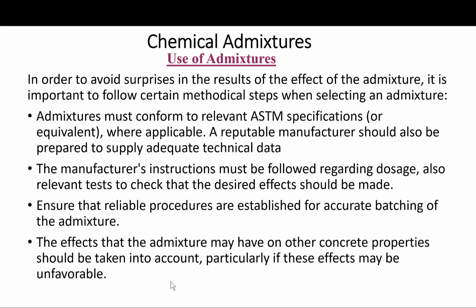So, following the instructions of the manufacturer when using an admixture, and more important though, you must run tests. The tests must be run on materials identical, or the same materials, to be used on that particular job.